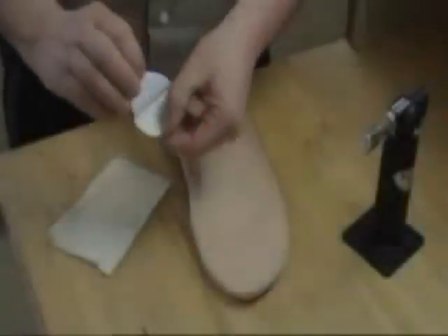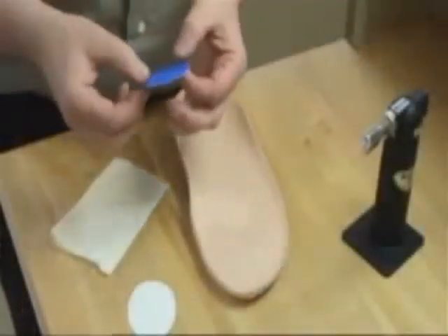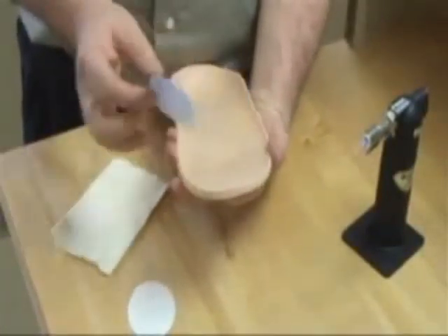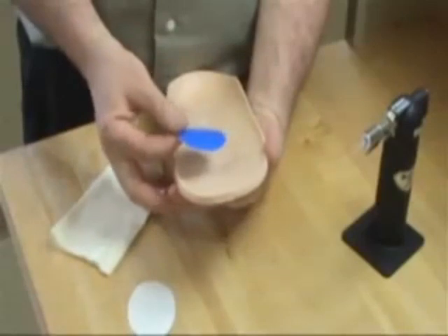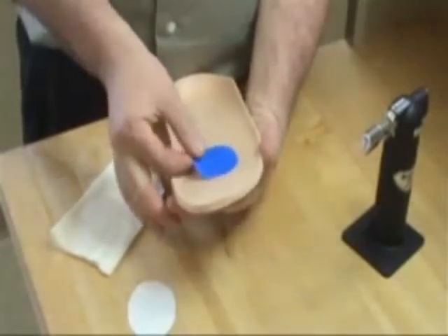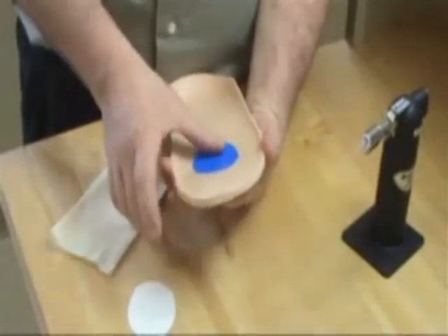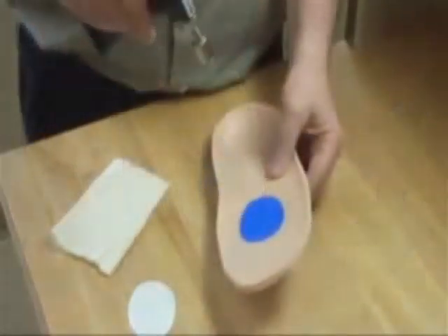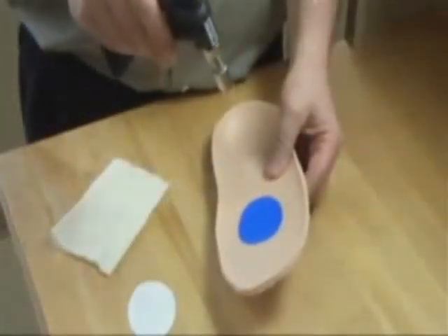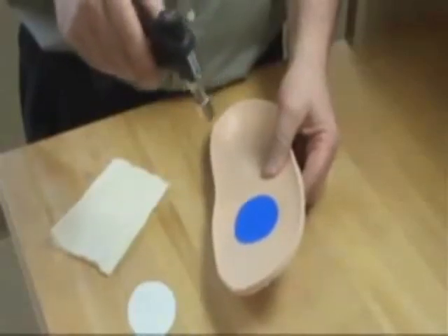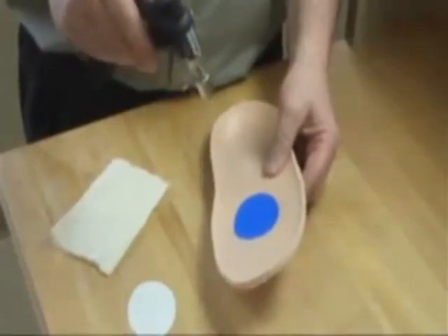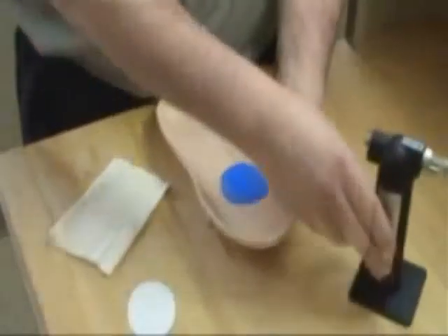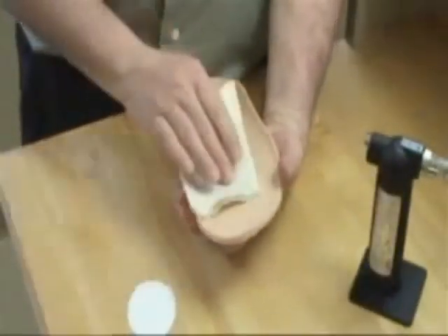As discussed previously, if there are very modest contours, the application is as simple as place and stick. The first segment shows the spot heating technique for applying the low-friction interface material into more complex contours. First, place the patch into place, just tacking down the perimeter of the patch. Using a focused heat source, spot heat the center area of the patch. The material will be ready when it appears slackened.